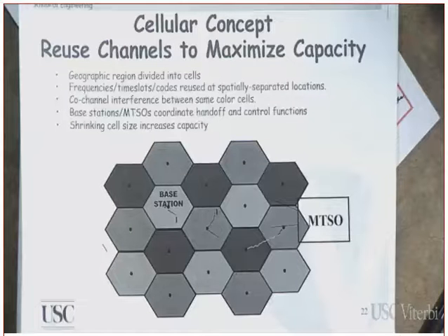And the receiver. Even that inversely proportional to the square of the distance is assuming we are operating in an open environment, like a rural environment. Rural means there are no tall buildings, not too many obstacles. But if you are working in a dense environment like, for example, downtown LA, the signal power will degrade inversely proportional to probably the distance to the power of 4, or even more than 4 in a dense environment or even in a suburban environment. Did you get this or not?